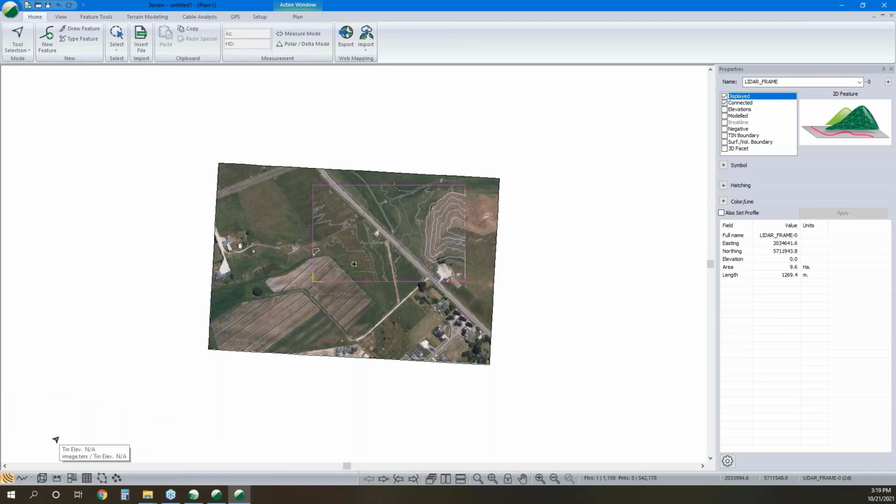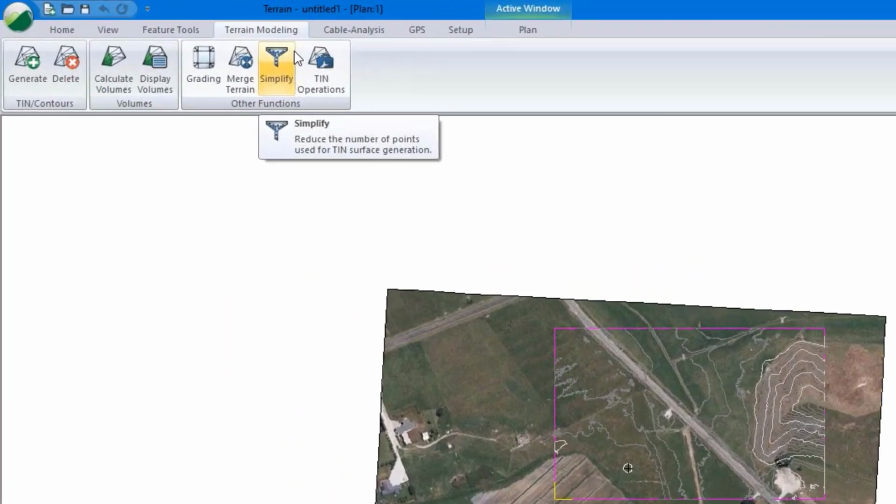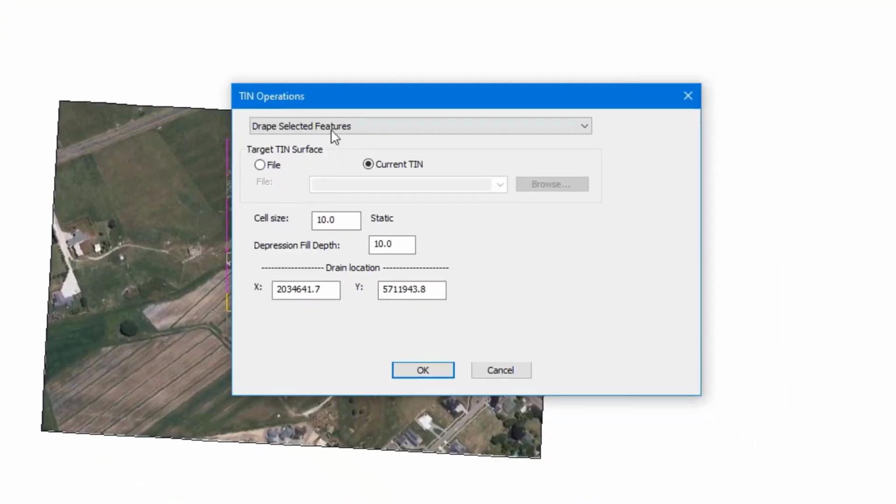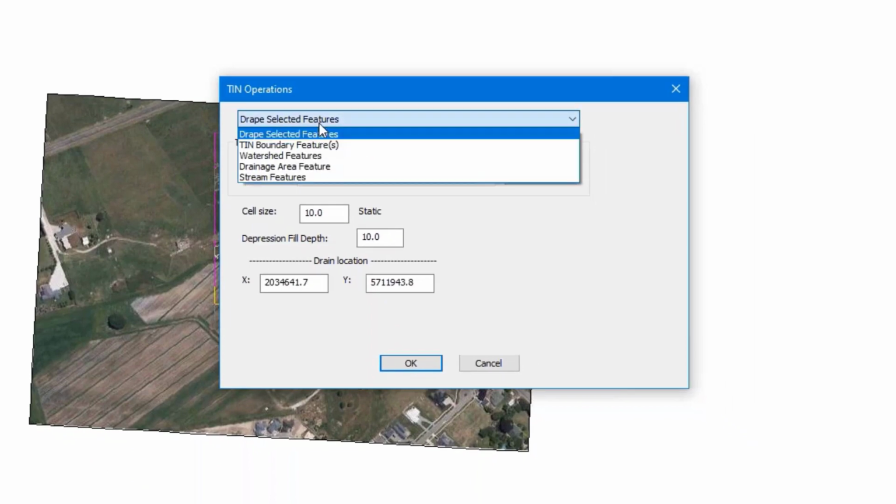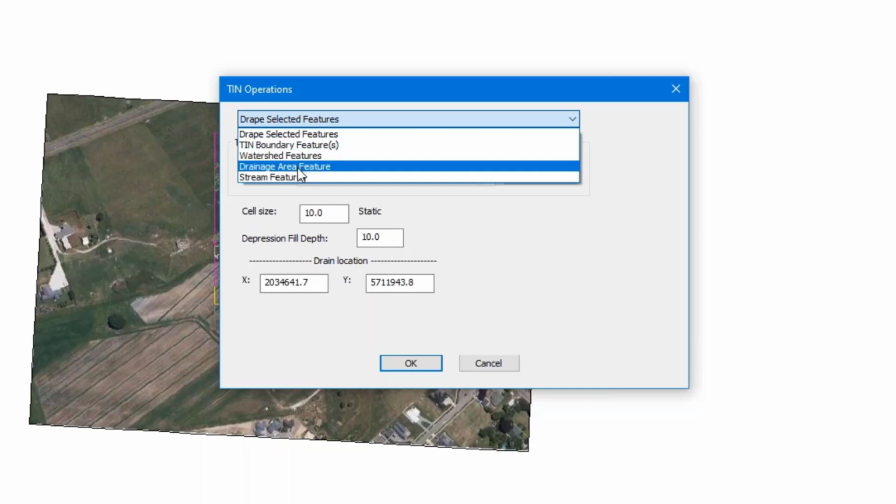Now, just before I jump out and do the rest of our project in location, I won't actually click them. They take a minute to run, and it's of course not fully released yet, so we're still refining things in it. But those extra features that I had mentioned for watershed calculations: in 10, we've added the ability to calculate your drainage area to a point if your TIN encompasses the entire drainage area, so it helps for hydrology calculations.